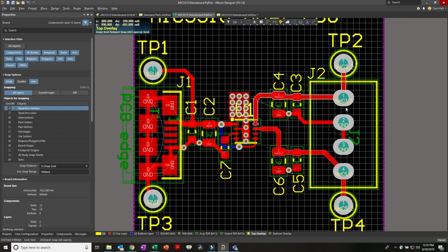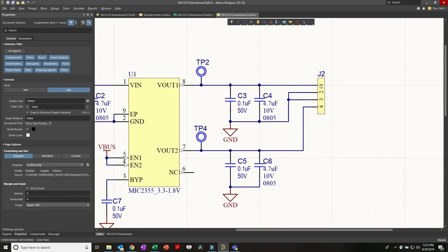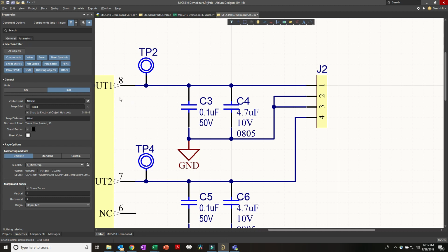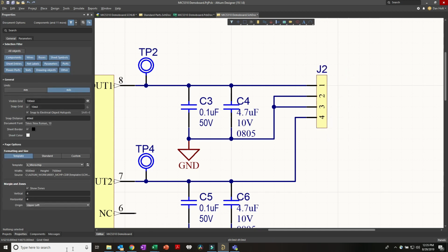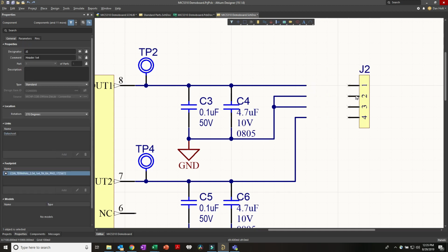This is what's so annoying. I wish the rotate wasn't even an option, quite honestly. You've just got to fuss with it to get it back to normal looking. Okay, so let's flip that around. Now, I can flip it around by literally rotating this connector, but you can see I really want this V out to go straight to this point. So much easier to just reverse the pin order 1 through 4 and call it 1 through 4 this way. So if I go back to my schematic, I really want pin 4 to be my output number 1.